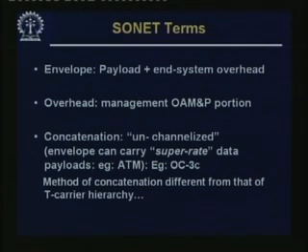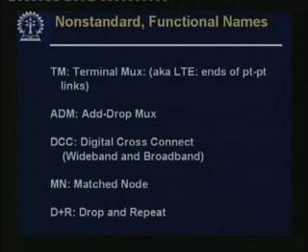So, this is just a SONET term. And other bits and bytes which are used for management, that means OAM and P portion, go as the overhead of SONET. Then there is this concept of concatenation, that means unchannelized. So, the envelope can carry super rate data payloads, for example, ATM etc. The method of concatenation is different from that of the T carrier hierarchy, we need not bother about it at the moment.